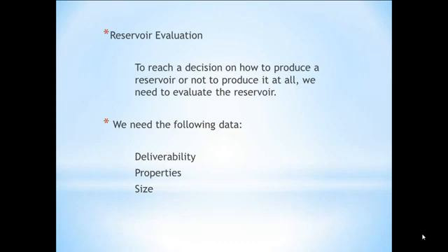we basically attempt to determine the reservoir conductivity, that is the KH product or the permeability thickness product, and reservoir pressure and reservoir limits. At the same time, we will sample the fluids and measure their physical properties. Now the KH factor basically governs how fast a fluid can flow to the well,